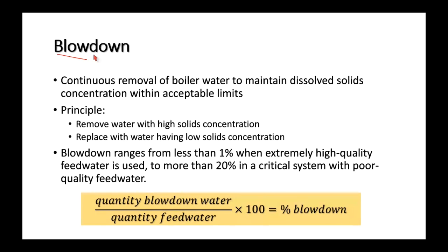We always have to differentiate between blow down and blow off, and that's because the ASME differentiates. So ASME says blow down is continuous, or it's from a water level control, like a low water cutoff. Okay, so that's what blowdown is.